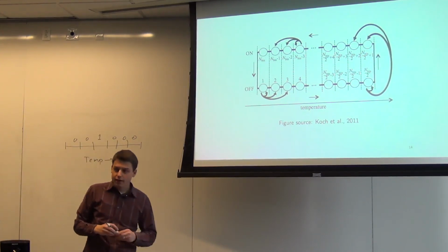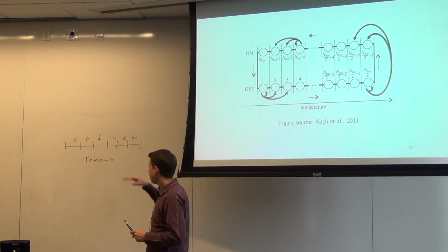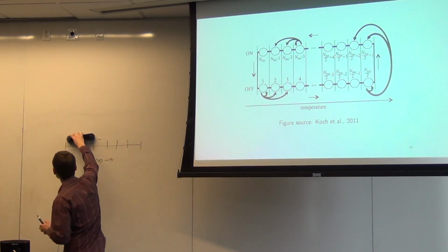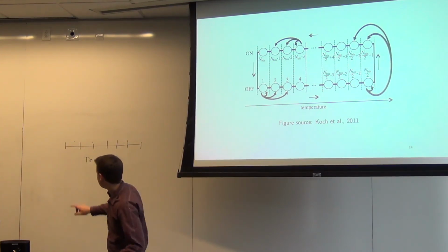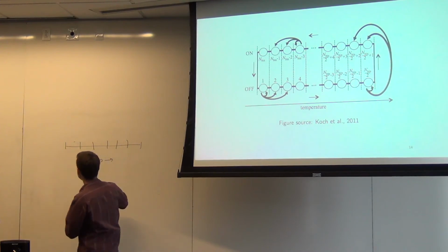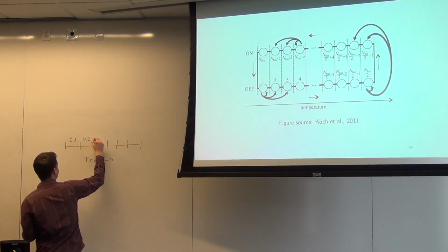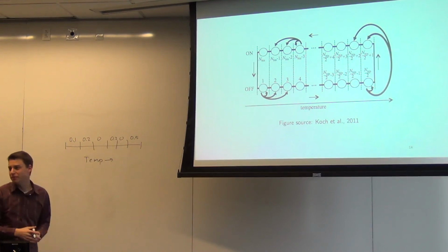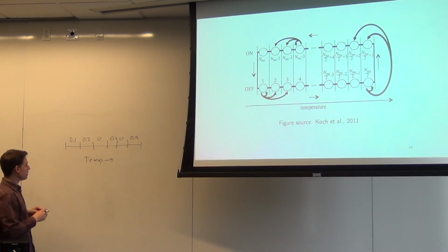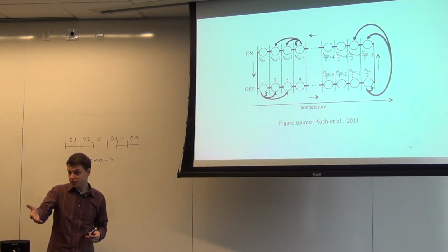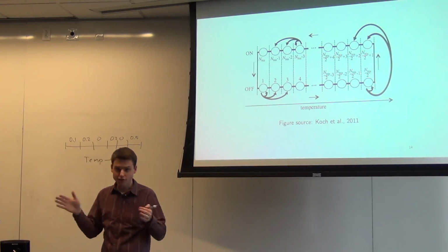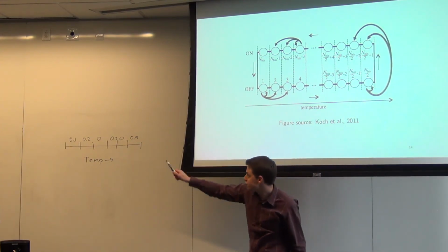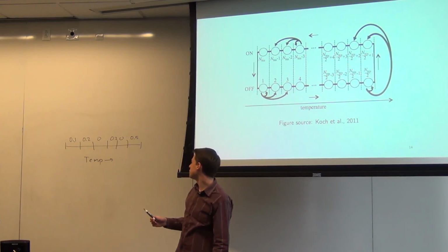What you can do instead is have the state be an actual probability vector that represents where everyone is. So instead of the state being this, you look at every single appliance and say, how many are in this position here, at the lower range of their temperature. So maybe 10% are there, 2% are there, 2% are there, 5% are there, and 0 everywhere else. This wouldn't really happen, but just say it's like that. Usually you have some in every state. So this is our new state. Now we've represented the state of all these hundreds of thousands of systems by just a single vector that's relatively small dimensional. And the n bin there is the number of chops you make for your state, or maybe the number of chops divided by 2 or something.